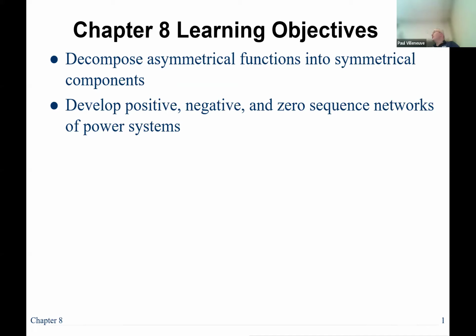So today we're going to introduce the concept of symmetrical components. The whole purpose of symmetrical components is to take systems that are unbalanced only at one point location, and make those systems more balanced. We don't actually use the term balance, because balance is when you have exactly the same magnitudes, but the phase shifts are 120 degrees. So that would have to be a balanced system.